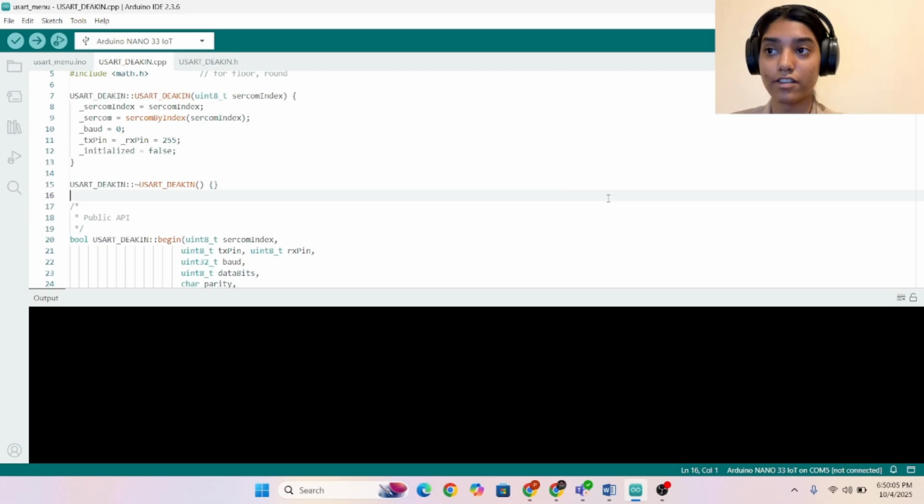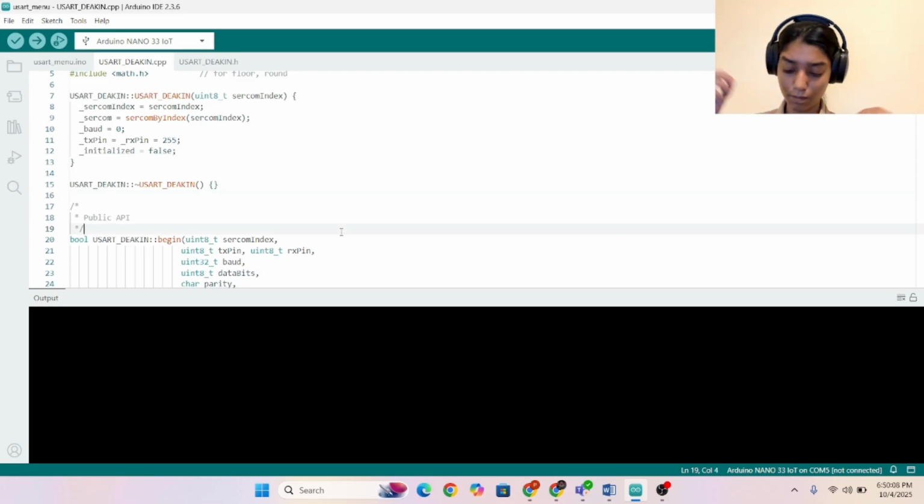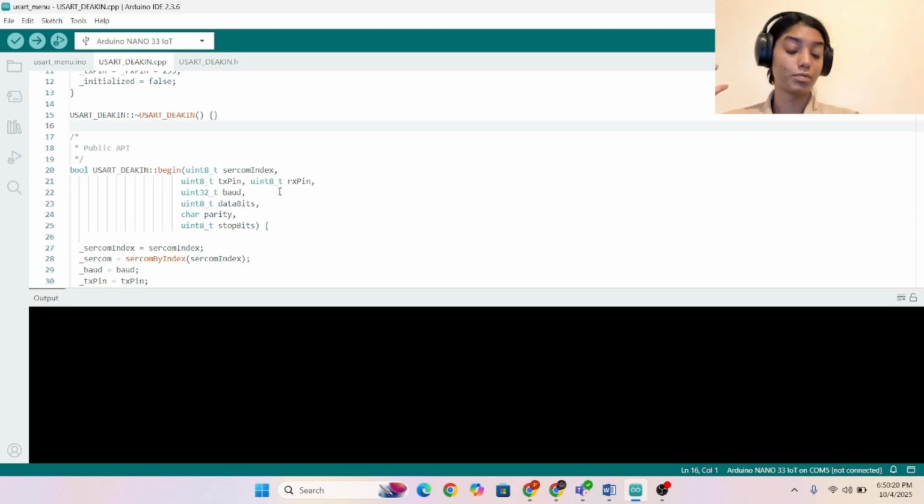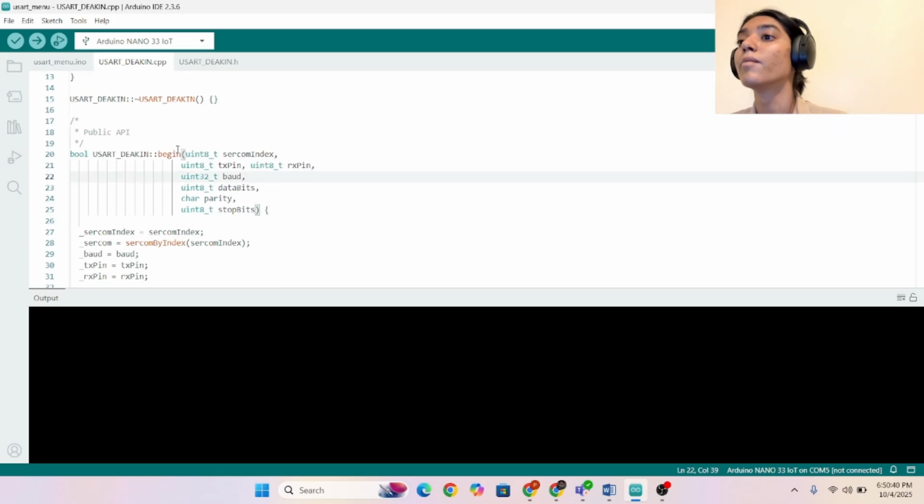our circuit reads from. And in order to make this circuit, I would be using one Arduino Nano IoT 33, and the RX pin would be directly connected to the transmitter pin. A person could work with multiple Arduino Nanos. The minimum would be two for that case, and then they could communicate between two devices. But just for this task, I just have one Arduino Nano IoT 33, so I just communicated with it all together with a single board and displayed it.